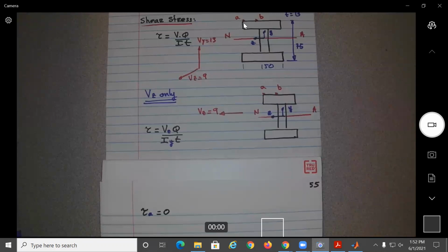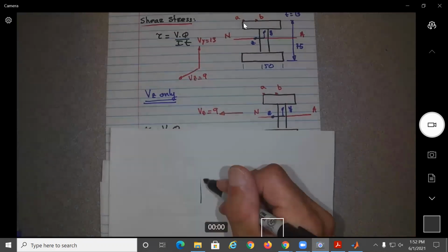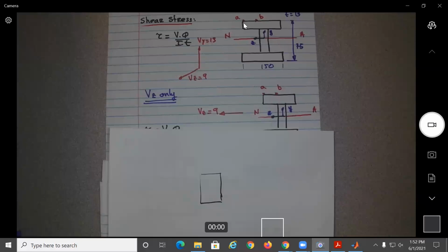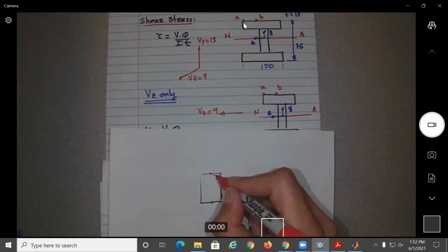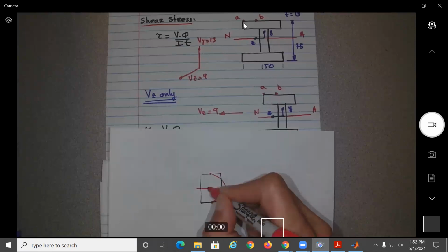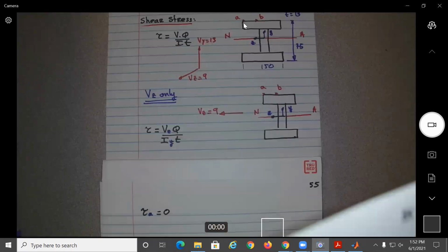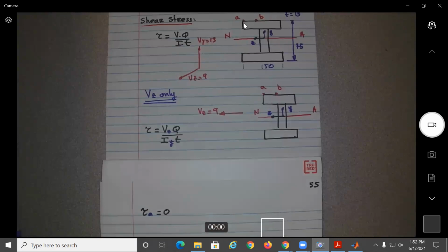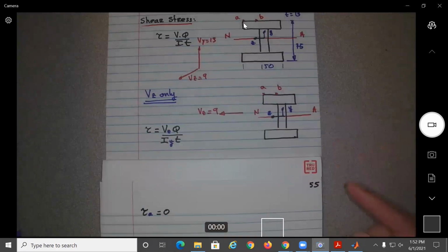I mean, guys, this is solid mechanics. Again, if you have a rectangular cross section, what is the distribution of the shear? I think we said last time, 0 at the top and the bottom because there is no area to shear against. And where would be the shear maximum? At the neutral axis. We haven't done anything new. So in this case, this is at the top, so shear is 0. Actually, it's going to be 0 no matter what, even for the other force, simply because there is no surface. So really, if you look at the equation, Q sub A will be equal to 0.